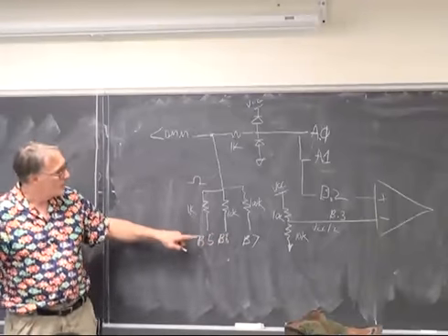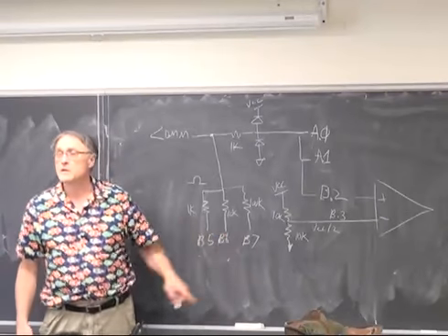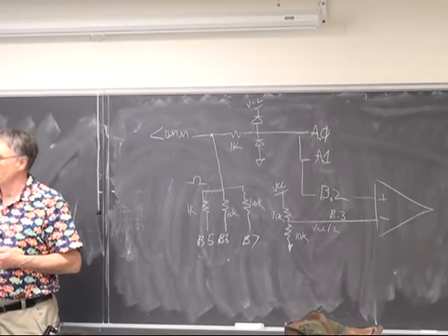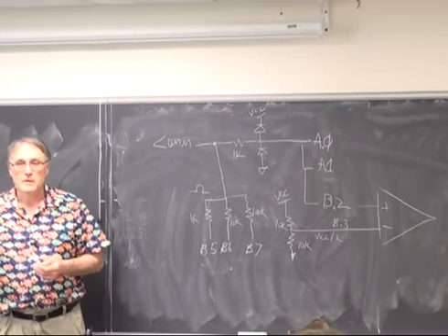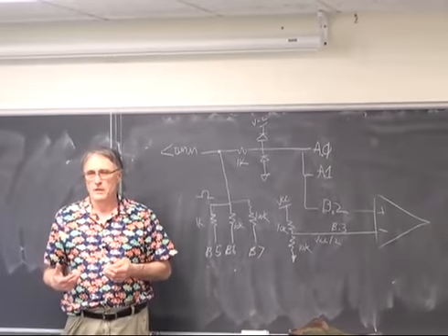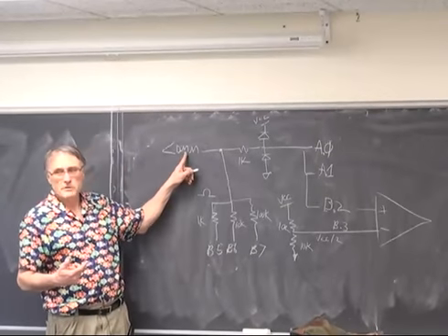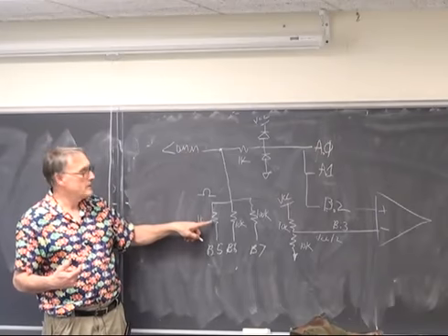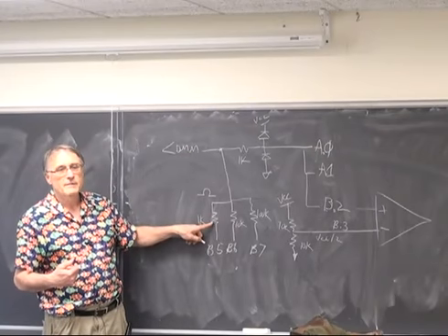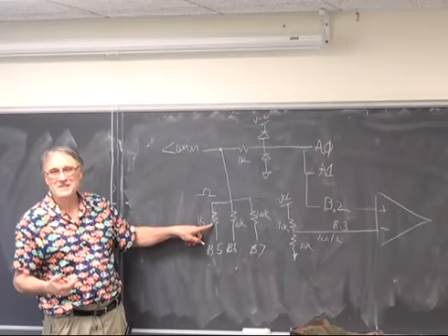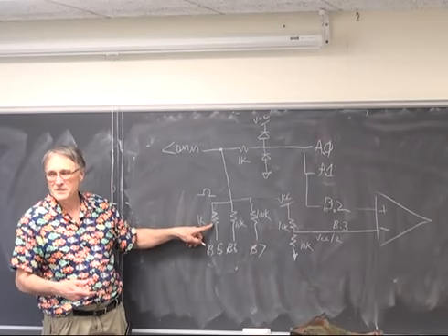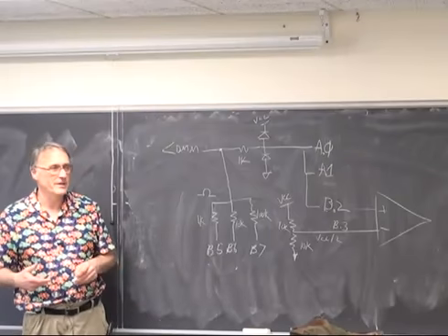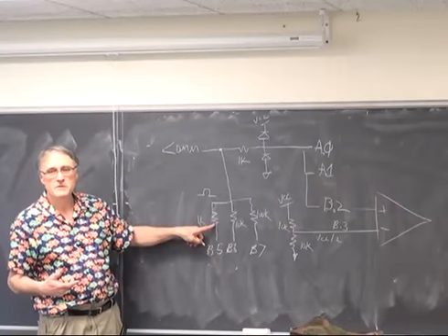Because you can choose which of these pins you want to turn off or on, you have the ability to auto scale. You get best sensitivity for a measured resistor if the resistance under test is not more than 9 times bigger than the resistance and not smaller than 1/9 of the resistance or so. Actually, you get best sensitivity if this resistor is about the same as this resistor.